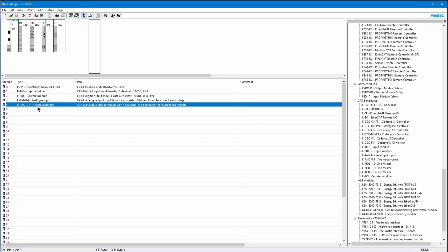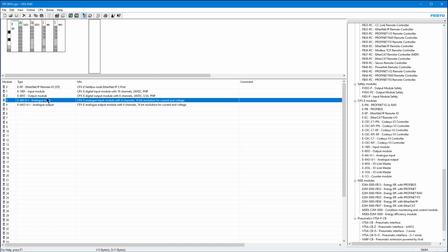The whole concept is that you are saving the image of all parameters, so that if any one module ever fails, when you replace that module, the PLC pushes the parameter values that were changed to the module when they're first powered on.